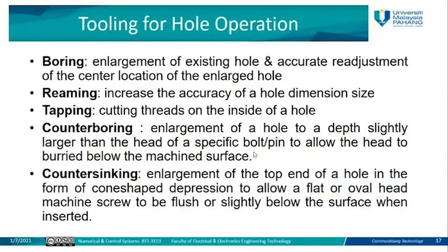Counter boring is also to enlarge the hole to a depth slightly larger than the head of the specific bolt or pin. Sometimes this drill is not used just to create a smooth hole, I mean a hole with a smooth side, but this hole will be created in order to fix some pins or bolts inside it. So counter boring here is used to enlarge the hole for the head of the specific bolt or pin, to allow the head to be buried below the machined surface.